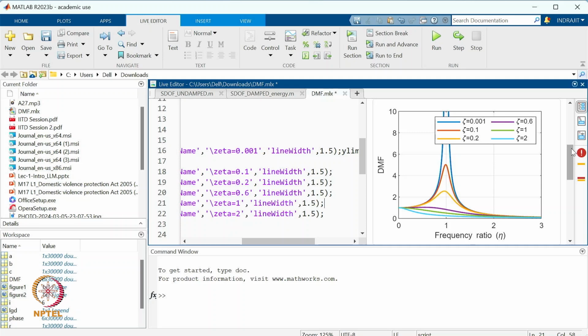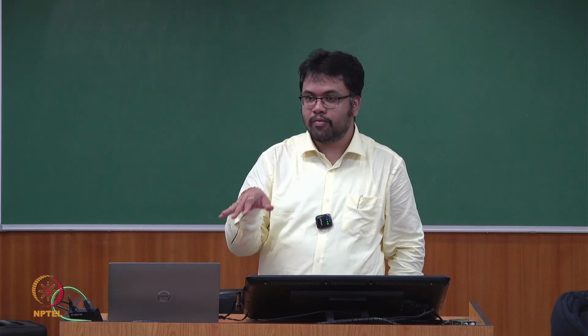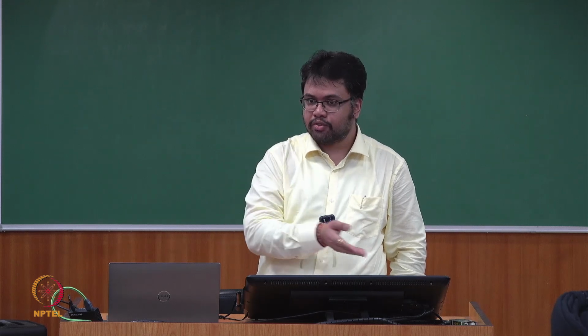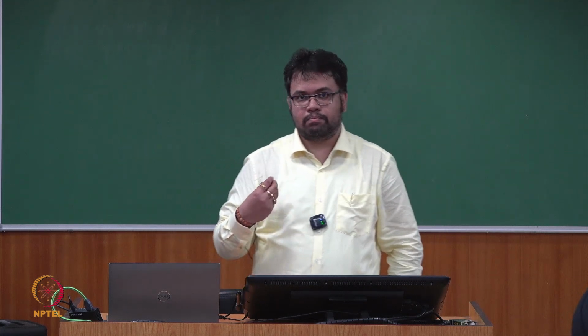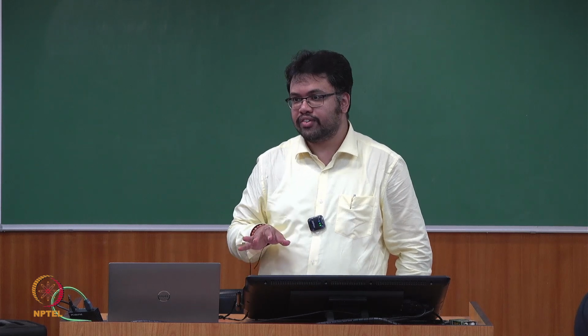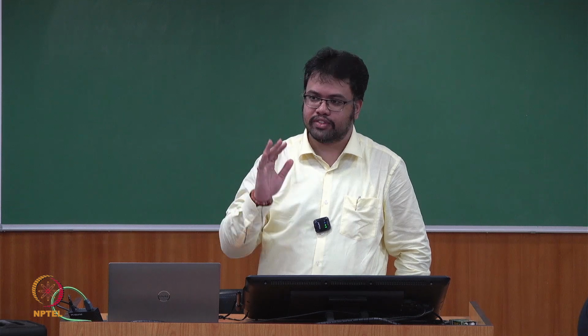So now if you go to the overdamped system also, your peaks are completely missing, and it is also going to the low frequency side. Okay, that makes sense. So the effect of resonance is completely vanished in the case of the critically damped or overdamped system.